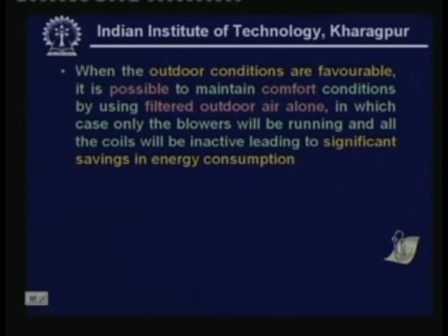And when the outdoor conditions are favorable, it is possible to maintain comfort conditions by using filtered outdoor air alone. That means you can switch off everything and just run the blower, in which case only the blowers will be running and all the coils will be inactive, leading to significant savings in energy consumption. So, when outdoor air is cool, let us say, then you do not have to use any cooling or dehumidifying coils, just run the blower and use full outdoor air and provide comfort.